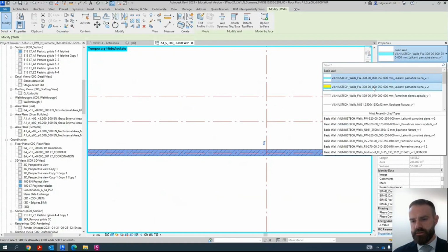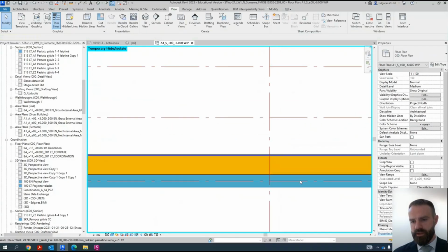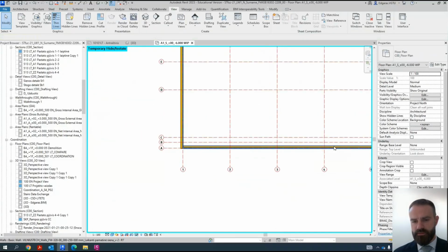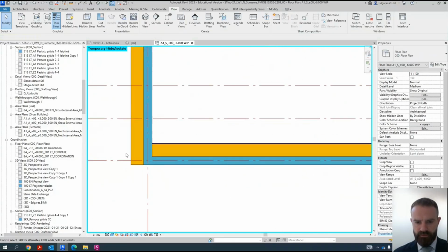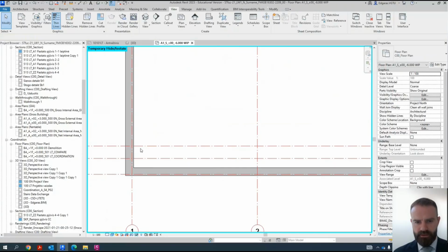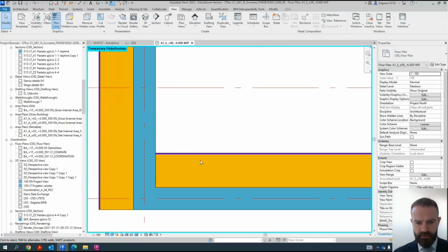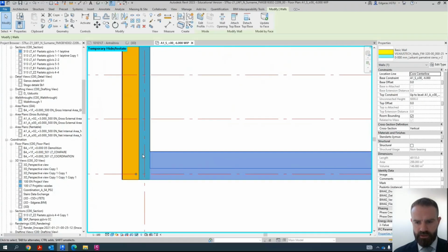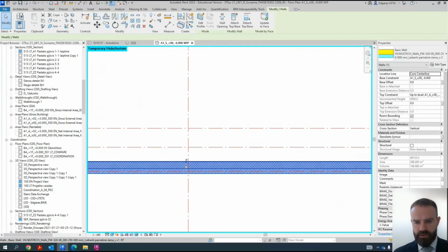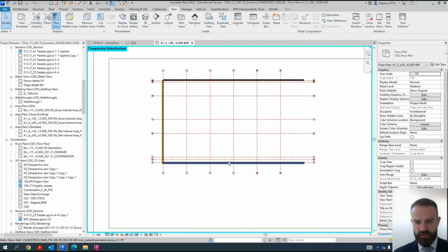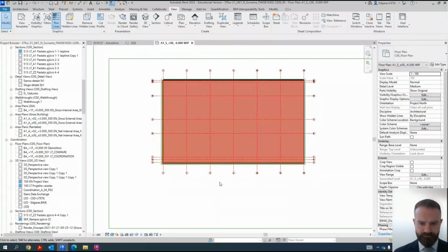And if I select wall, all the insulation material goes inside of the building. So this is wrong. And if I use coarse representation, it looks nice, everything works nice. But if I put more details, I see the wall is in the wrong position. So I need to go and fix all the elements.